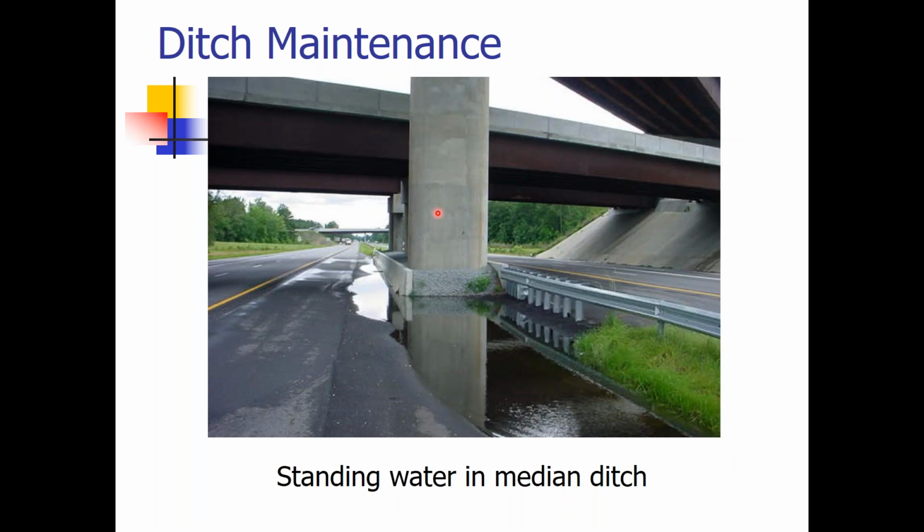This was a design at an interchange. It was turned over to the state, and you can very clearly see there's standing water in this median area. And I went back out to this area, and what I could not find was an inlet. I could not find where that water is supposed to flow. This probably is not the design that we need to be able to maintain.